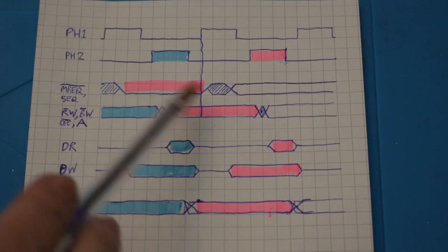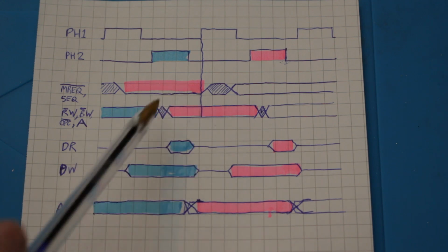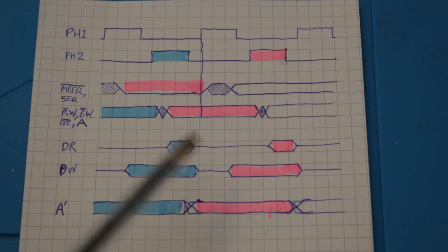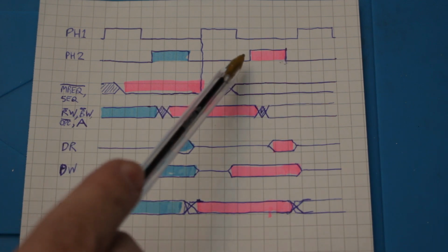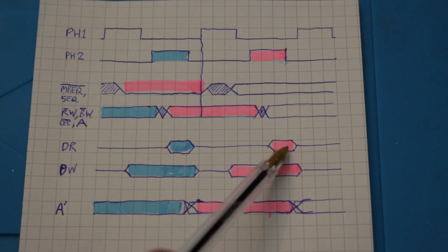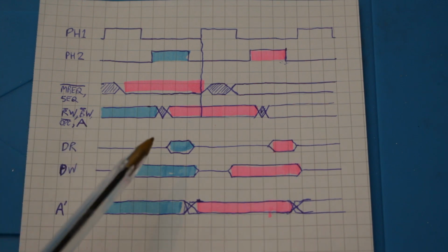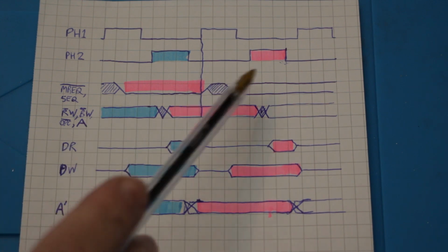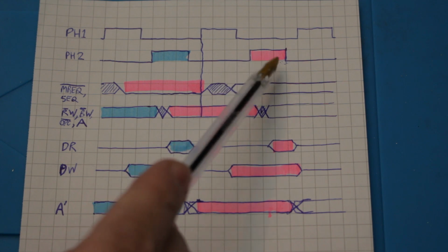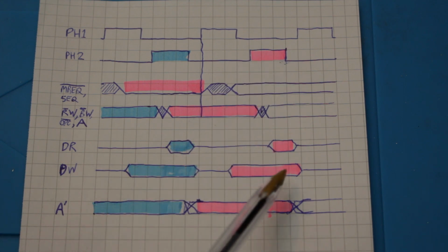And what that means is that when we've done this latching, we're basically going to be able to treat the phi 2 high period just like we would on a 6502. When we're reading data, we can just use that period to tell the ROM or RAM to start outputting data, and it will definitely be fine by the end of the cycle that way around. And when we're writing data, we can again just tell the RAM to accept new data for that entire period, and it only really cares what happens at the very end. But the CPU is going to keep that data valid throughout.